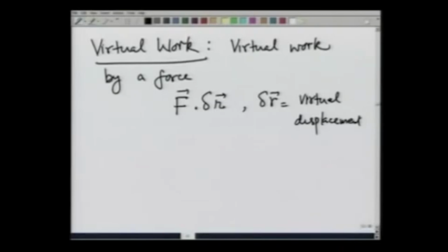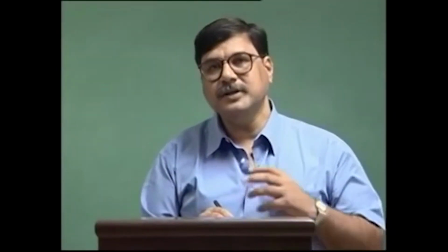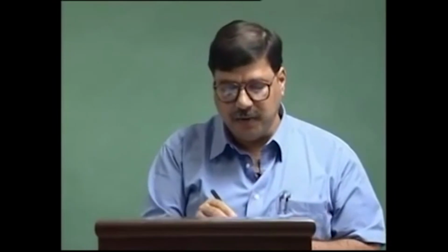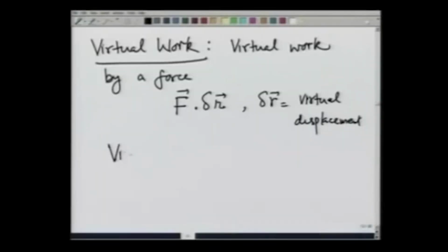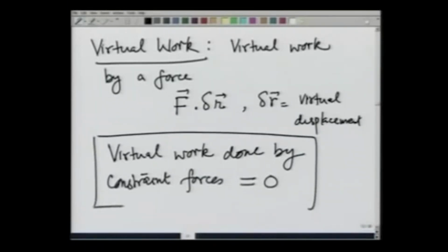Naturally, if I am doing a displacement consistent with the constraints, and we have already seen that the constraint forces do not do any work, then virtual work done by constraint forces is equal to 0. This is a very, very important statement, and that makes the development of the method of virtual work possible.